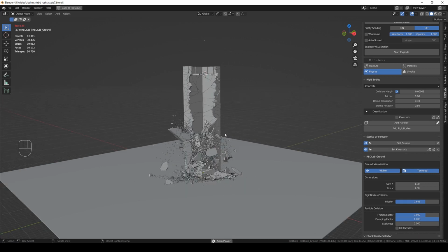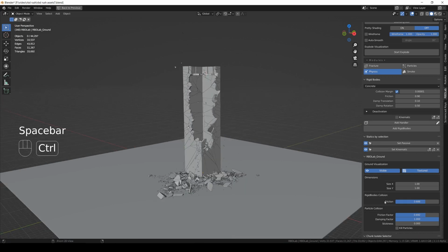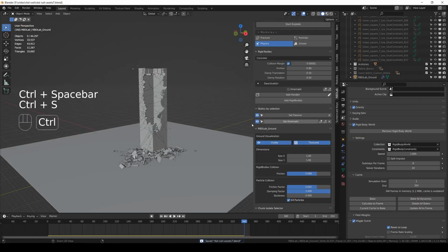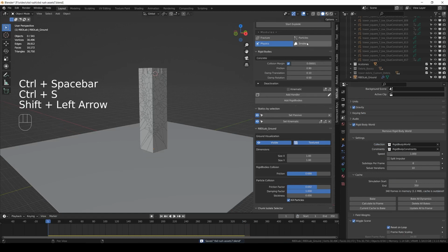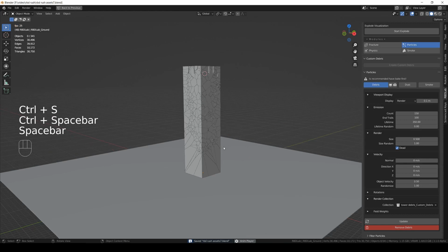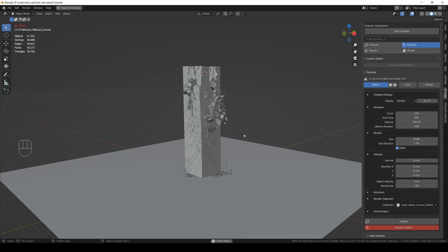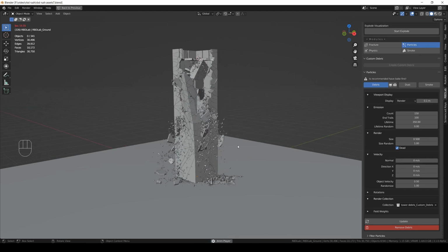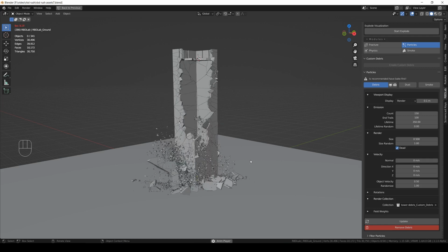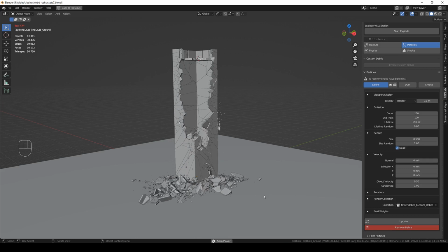So what I'm gonna do to fix this, don't worry, is to just activate the kill particles for the ground. And also, if you go in the particles setting, you can activate the dead option. Click on update, and now when the particles collide with the floor, they will just stop moving. And it's really great that you can just do it in one click. Thanks to the addon, because actually I tried to do it manually in some other works, and the dead option is one of the Blender functions that you cannot just click once for all the particle systems for some reason. I tried the hold, alt and click, I tried everything. So this addon another time is proving to rock and roll.